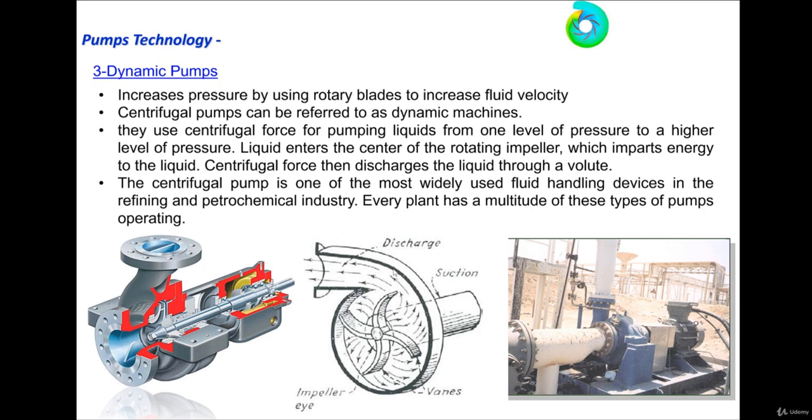So the total pressure has a dynamic part, depending on the velocity, and a static part. And in the static part, if you decelerate the flow, automatically the static pressure will increase, and the static pressure will be read on the gauge.